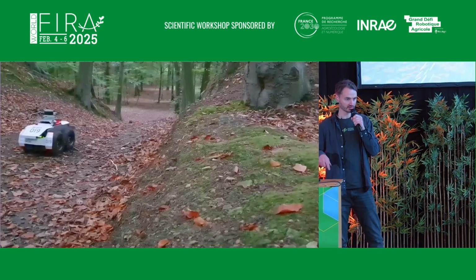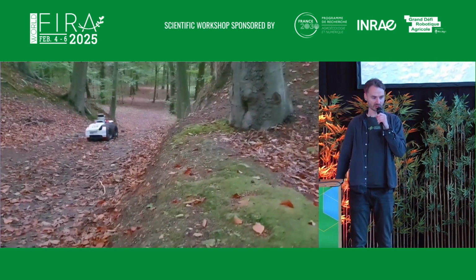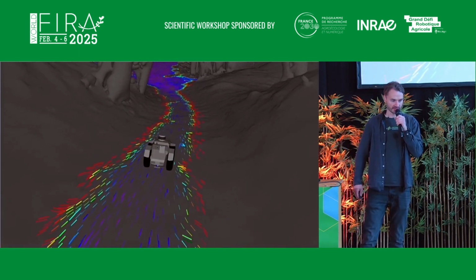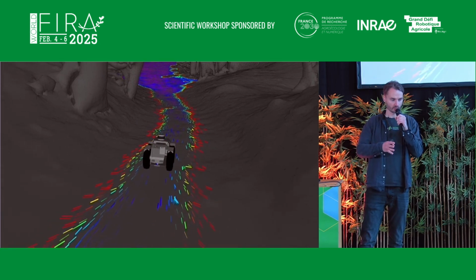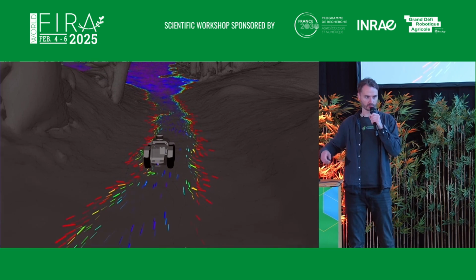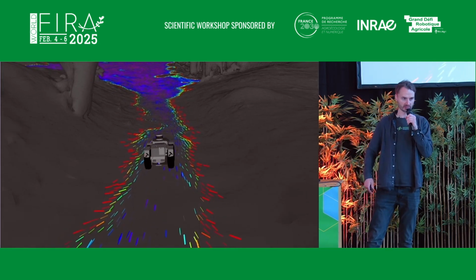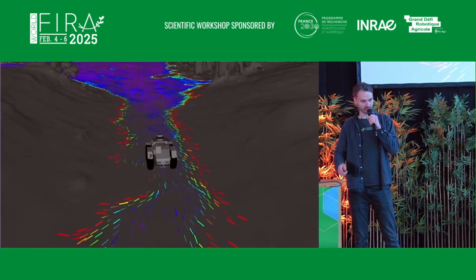The vector field is computed in under a second to any goal position you want. And the nice thing is, if you move the robot from one position to a position a meter or 10 meters away, it directly knows again where it needs to go, because you have this vector field. And here you see what is drivable and what is not.